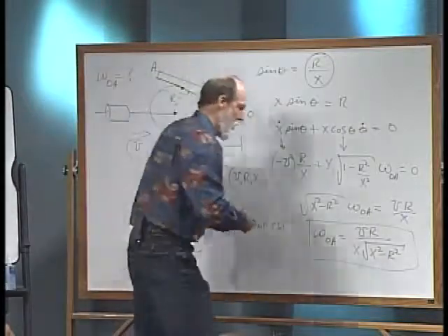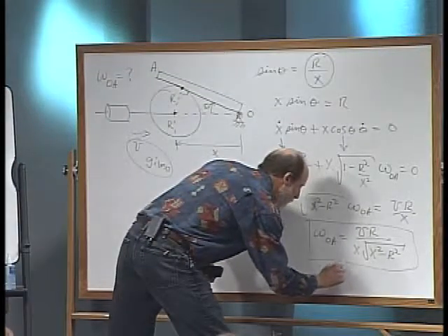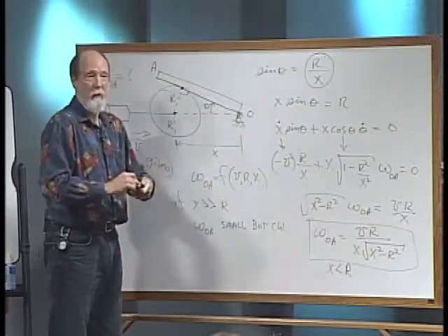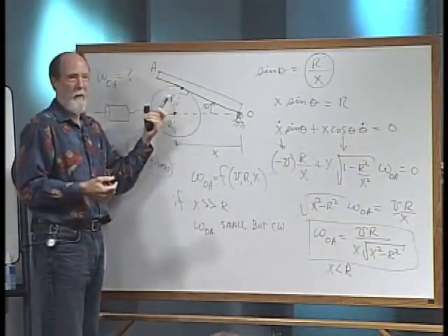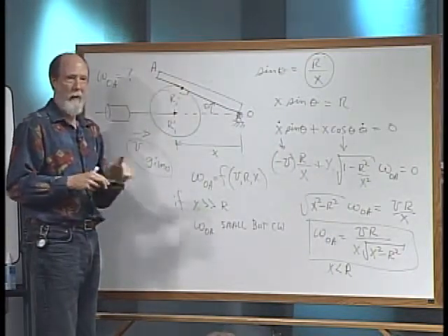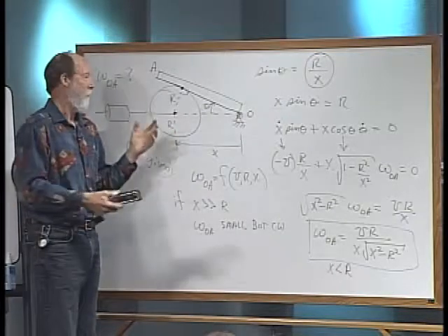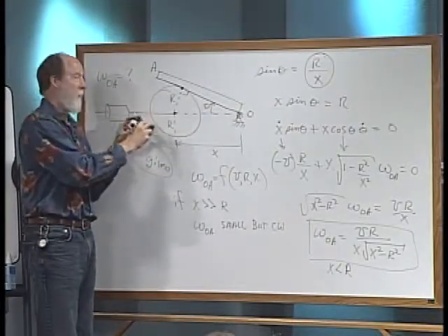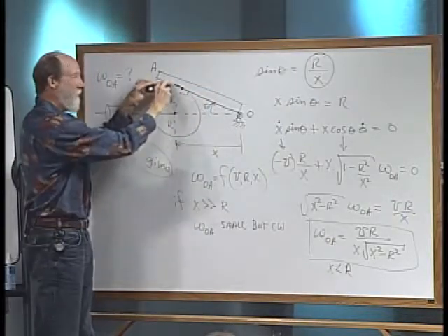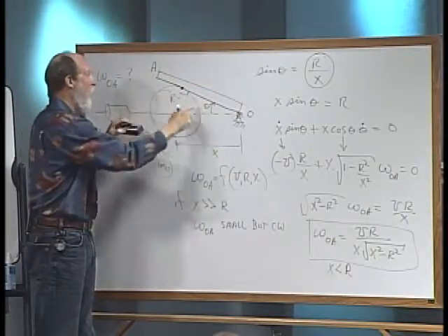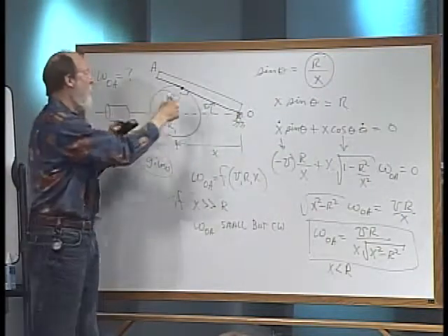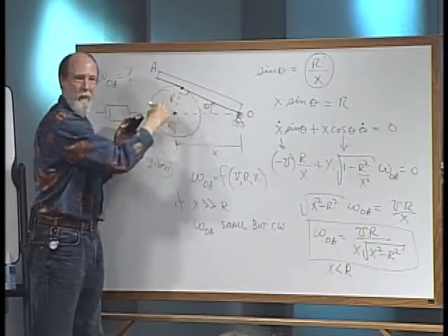Okay. In addition to this would be to give the disc or wheel a vertical offset. Yeah, oh yeah. You can build these mechanisms up and give them all kinds of interesting features to alter the effects. And matter of fact, that's the way you do the design. You might start with something like this, then you might go, hold it, this thing isn't really doing what I want it to do. I'm going to give this maybe a vertical offset, or maybe I might even make this wheel, like Daniel and I were talking after class the other day, maybe make this elliptical or some other cam shape.